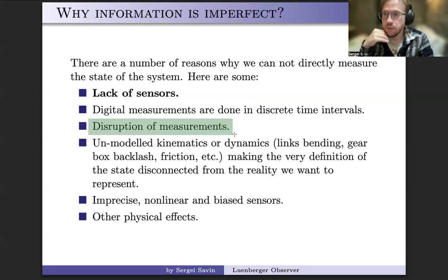It depends, right? But what I'm trying to say is sometimes you simply cannot get a measurement for a short period of time. On average, you have this measurement, but right now you don't. Right now you don't have an x. And notice, if you're going to do u equals kx control, you have to have x. You cannot just decide, okay, right now we cannot do anything, but in 5 minutes we'll be back. You have to control all the time.